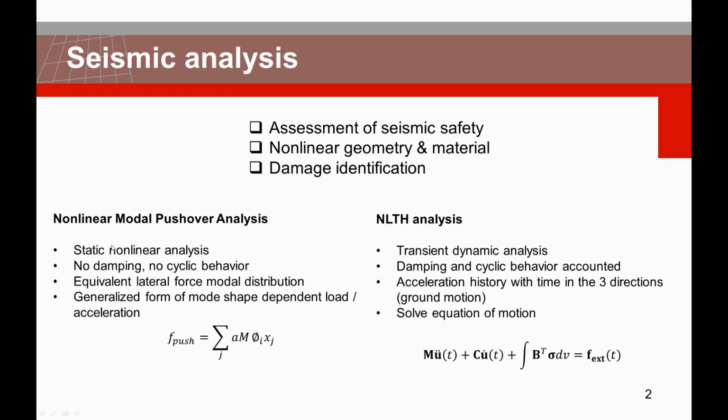In the nonlinear pushover analysis, we have a static nonlinear analysis where no damping or cyclic behavior is considered. The lateral force is equivalent to the modal distribution, and this is automatically computed in DYANA. So DYANA calculates this lateral force based on the mode shape.